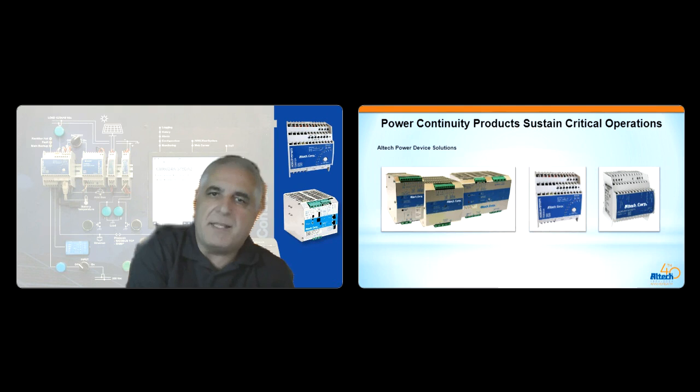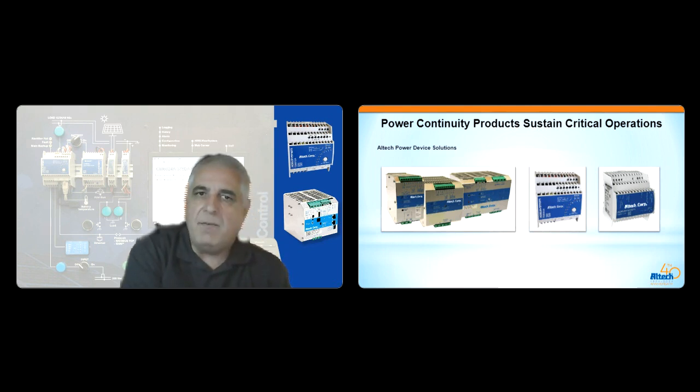When selecting a UPS system, you should take several key considerations. Most important will be the load capacity. You have to determine the power requirements of the equipment you plan to connect to the UPS and choose a system with a load capacity capable of supporting the connected devices. The other key feature will be topology. Different UPS topologies offer various levels of protection and efficiency. Select a UPS topology that best suits the needs of your application in terms of reliability and performance.